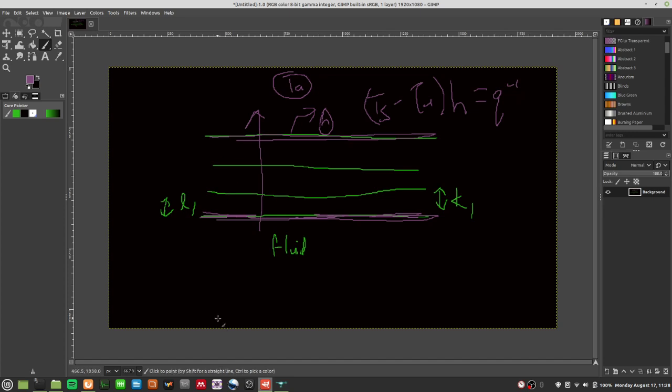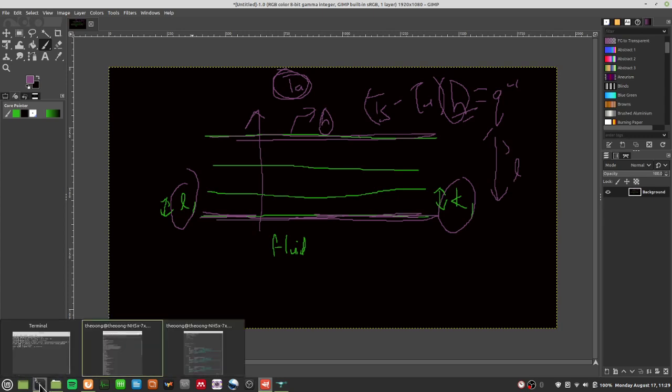So there are two things you can play with. One is the thickness and thermal conductivity of the layers here. The other is the heat transfer coefficient between this surface temperature and this ambient temperature. Of course, you can make this thermal conductivity high and this length very low. But in the case of a heat exchanger, you want to make sure that thermal conductivity here is low because you're trying to insulate this whole thing. So you can simulate that even.